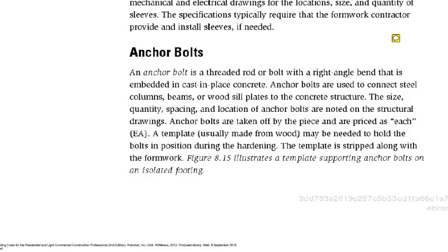Similarly, you're going to have anchor bolts that you're going to need if you've got a footing wall of some sort or an isolated pier, and you have to account for placing the anchor bolt in. If you forget putting the anchor bolts in, then you're going to end up generally doing the work over again. You may in some cases be able to talk a designer into letting you drill or epoxy something in, but I for one wouldn't allow you to do it. You take the footing out and start over again and do it right.